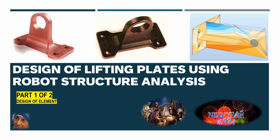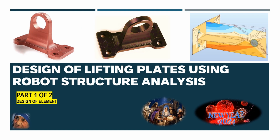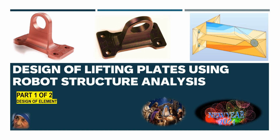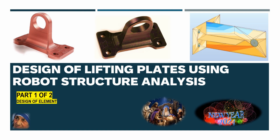In the first part, we are going to model this kind of plate in Robot Structural Analysis. We are going to apply assumed or tentative load values, maybe 5 ton lifting capacity. Then we are going to do the design and analysis. After that analysis, we are going to check the stress value, which should be less than the yield stress of the grade of steel plate which we had assumed. So this part 1 will explain how to design the element.